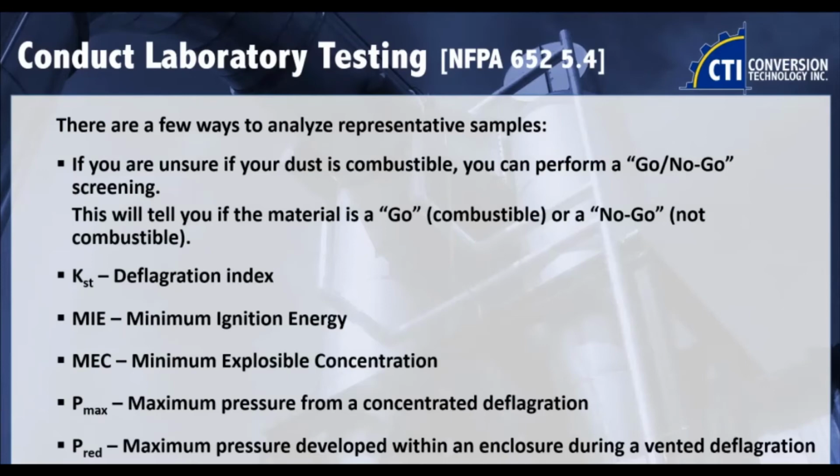And then P-red is the maximum pressure developed in the explosion, or excuse me, in the enclosure during venting. The KST and Pmax is typically what you would do. The other values get tested. You would need those for sizing of deflagration relief or protection systems.